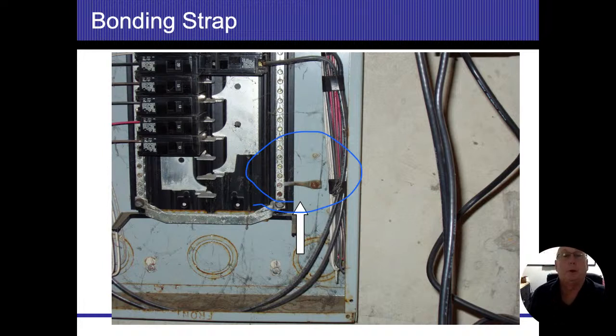Anything that ties to both are going to go ahead and connect it. So if any energized conductors come loose, energize my box, then that's going to go ahead and energize my neutral wire. All right. We do have one question up here,